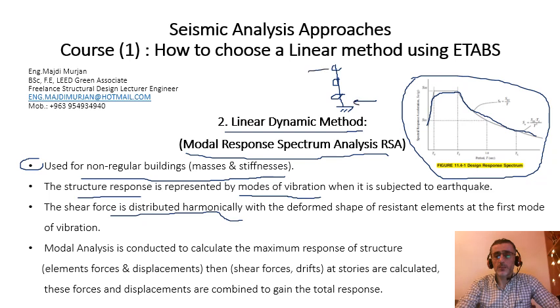their first mode of vibration, and the modal analysis will be conducted to calculate the maximum response of the structure, either element forces or displacements, and the shear forces and drifts at stories will be calculated and combined to obtain the total response.